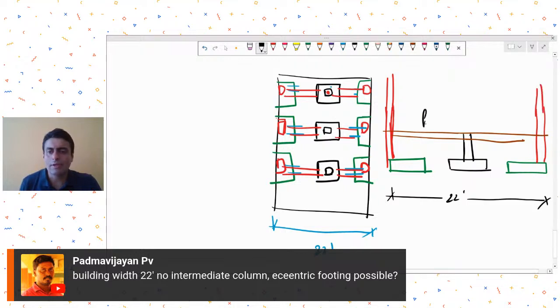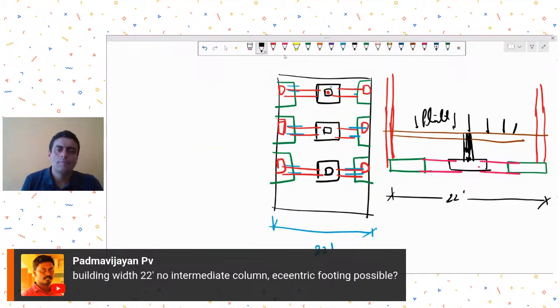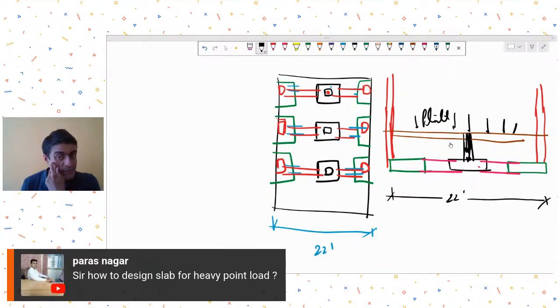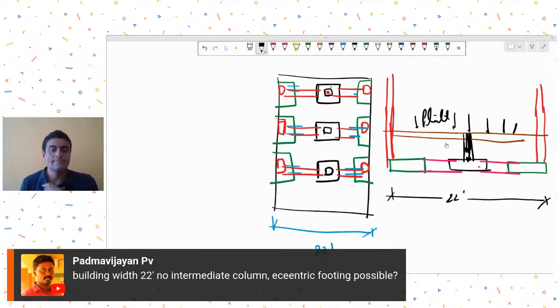So whatever load will be there on the plinth slab, some proportion of it will be transferred to this stub column, and that will help to keep this tie beam held down, and this will be effective. Okay, all right. So that is one of the strategies you could adopt over here. Is that clear? So providing intermediate stub columns with,